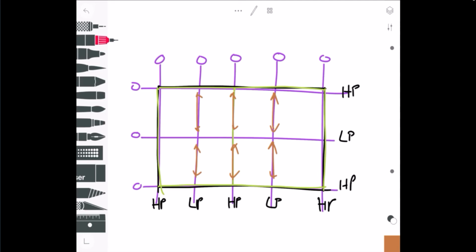So what that means is these two beams here are going to be flat. They're going to be at a certain height, and it should be the same height as the one on this end and the one on this end. Now the ones on these two ends, because the joists are running this way, these two beams are actually raised a little bit because there's no joist seat, but that's besides the point. The point is all the green areas, the beams are flat.